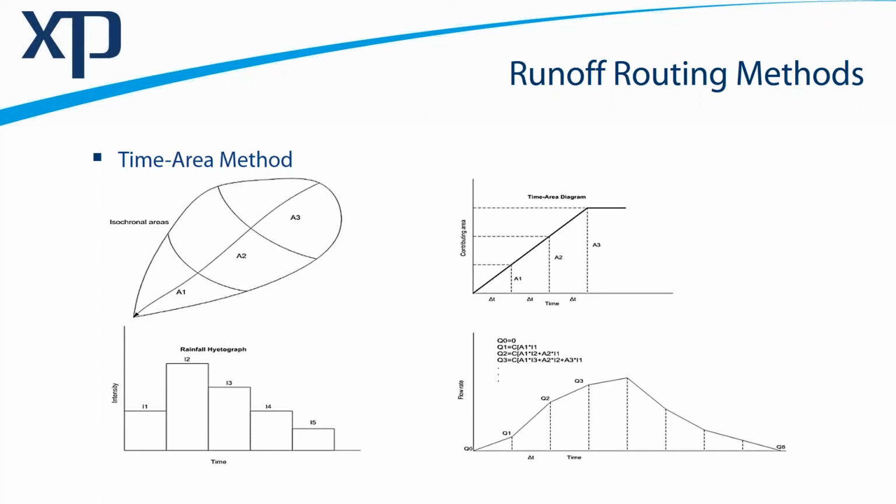There are some limitations to this method, of course, like all good methods. It doesn't work very well with particularly large catchments. If we had a time of concentration, it's not a parameter I talk about a lot, but anything over 24 hours, the time area method is not necessarily for you. So 24 hours is a bit of a limit.